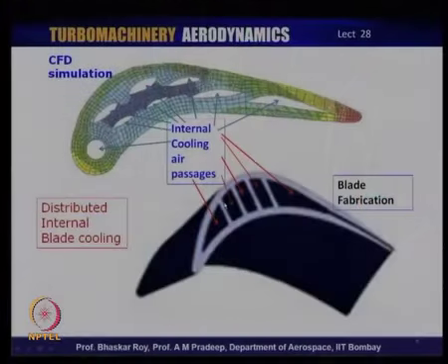And then of course, as you can see, you have the technology in which these shapes are created. Now, these shapes carry a certain amount of cooling air, and as you can see here, this has been created. Finally, it will exit through the trailing edge. As I was mentioning, trailing edge cooling is a problem, whereas the trailing edge, it is known, is a hot spot.